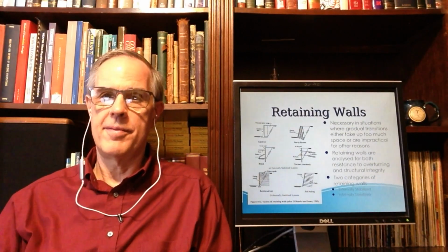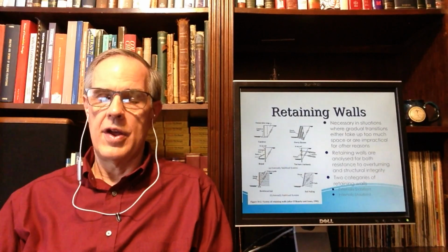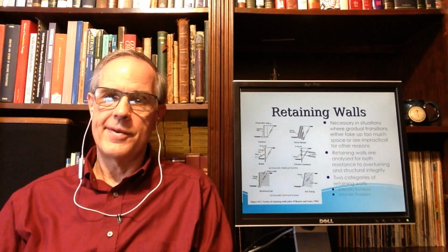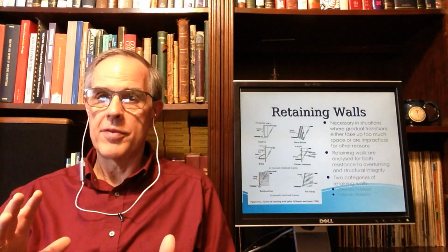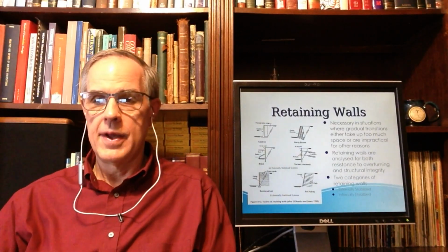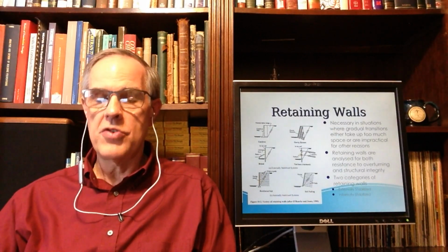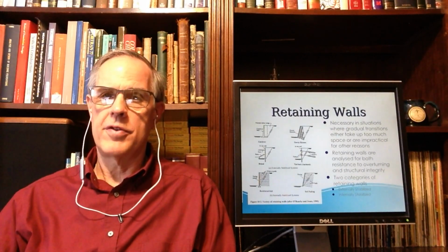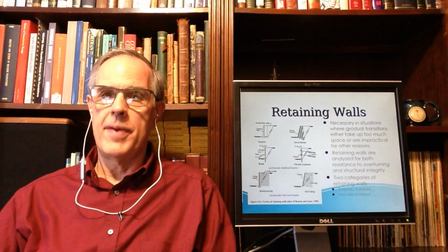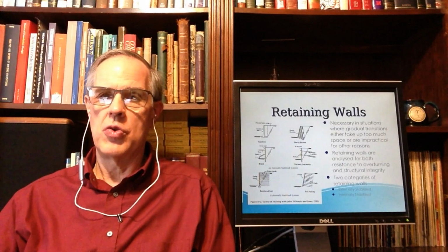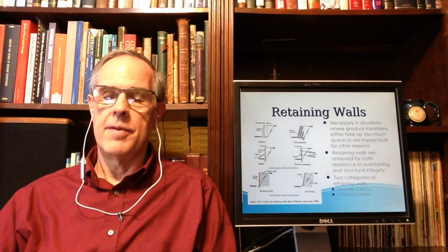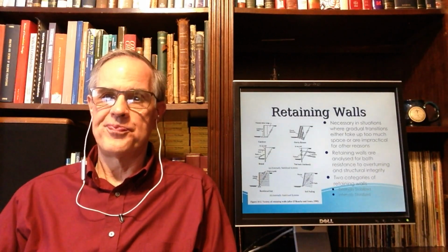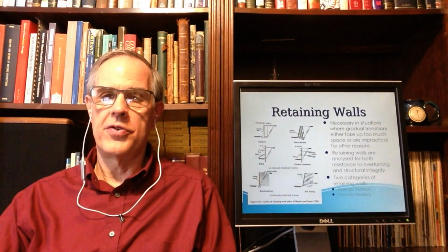They're stabilized by some external means, either supports or in some cases the weight of the wall itself or balancing earth pressures or whatever. And then there are internally stabilized walls. MSE walls are primarily where the stabilization of the wall comes from the internal workings of the wall, particularly with the way that MSE strips make their own earth support space.